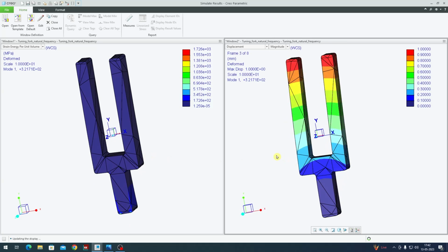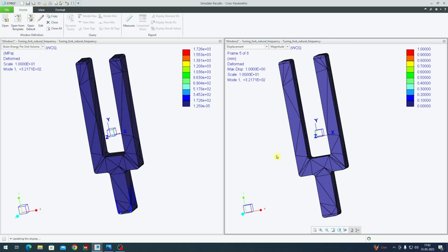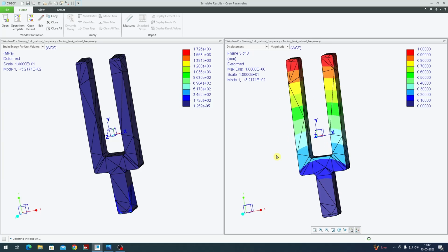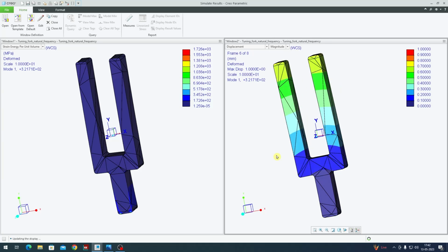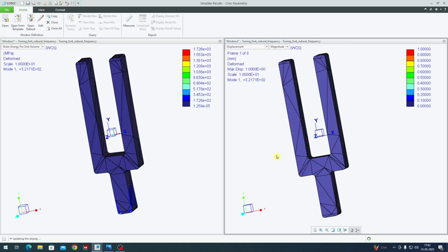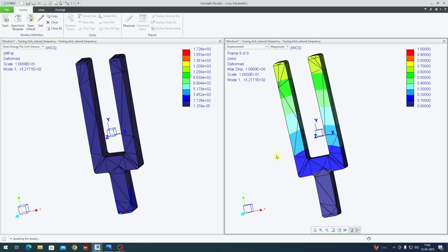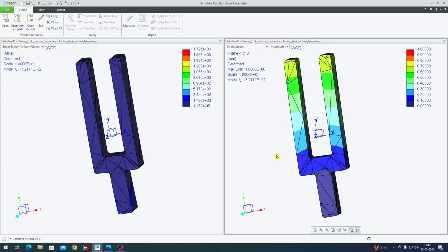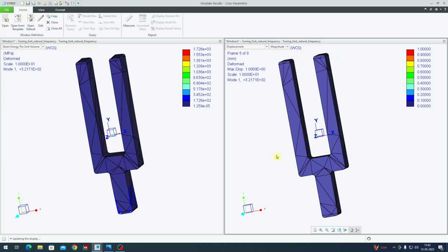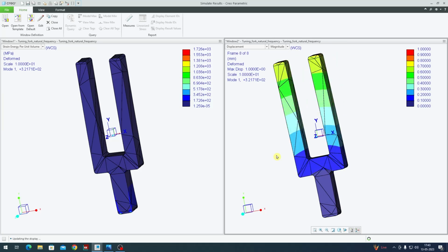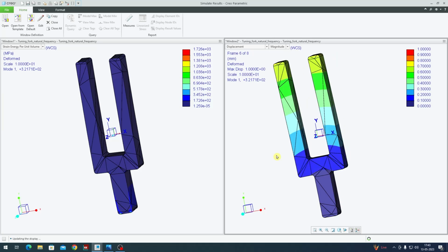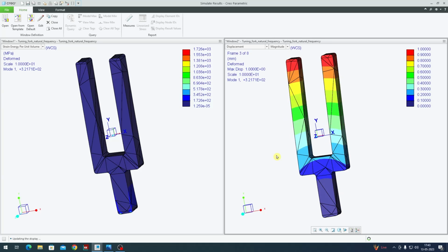So what we have learned here is how to take a particular component, perform modal analysis, and how do we take a look at the results like stress and strain energy. So keep in mind that displacement and strain are not absolute values. You should not take it in a holistic fashion where that's the absolute value. In real case as well, we can take the frequencies close to what it is in reality, but I should not consider stress or strain energy for absolute values. It is a good indicator. We can maybe use it for a comparative analysis between two different designs.